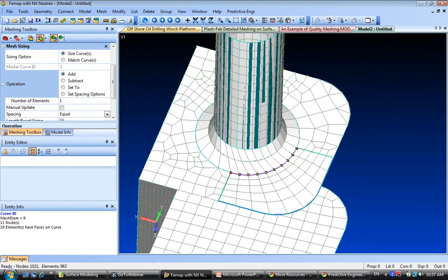The reason this is important, on plate elements, any sort of isoparametric element, 4-sided tetrahedrals, 6-sided bricks, plate elements, is that the perfect element is 1 by 1. And for a solid, it's 1 by 1 by 1. You get perfect integration, perfect matching of stiffness.